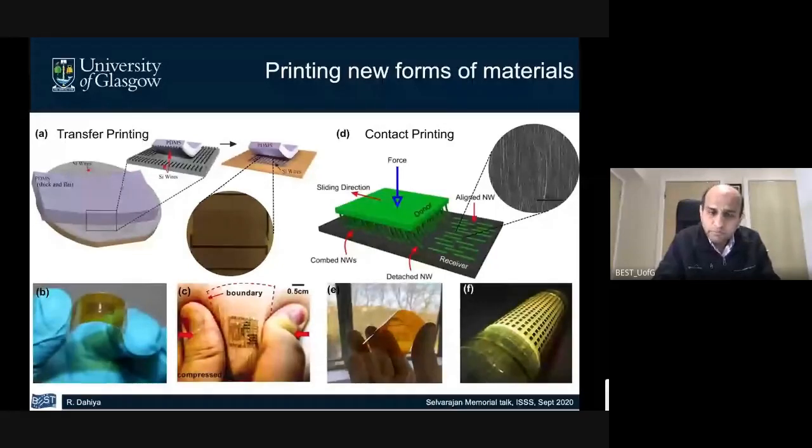There are various groups exploring printed electronics, but mostly the research so far has focused on organic polymers, organic semiconductors. What we do is we print inorganic semiconductors, and the reason is simple: mobility is quite high, and that leads to high performance. And high performance is pretty much needed in a range of applications, be it smart cities, be it IoT, wearable systems, etc., where communication and computation are needed. For example, about 500 megahertz switching frequency is what you need.